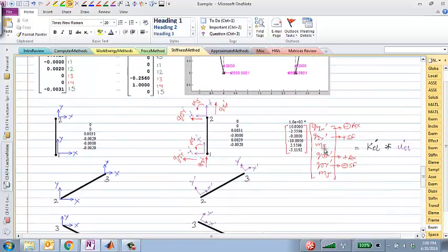And finally, for the moment, which moment is positive bending moment and which is negative? Mi is negative, Mj is the positive bending moment for this element, right? So indeed, this is negative bending moment, and this is positive bending moment. So if I look at element 3, this is 0, as it should be because it's a hinge at the bottom, and this is negative 5.11.